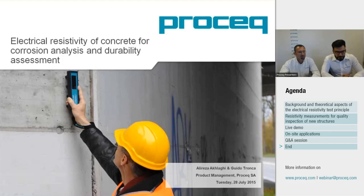Now I've got another question here. Let's see. Does corrosion inhibitor calcium nitrite in the concrete affect the resistivity reading? Absolutely yes. And they will decrease resistivity specifically.